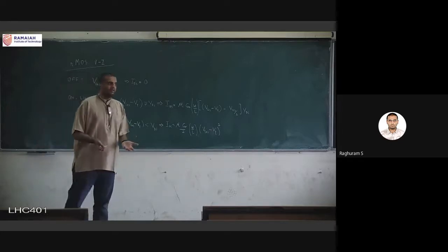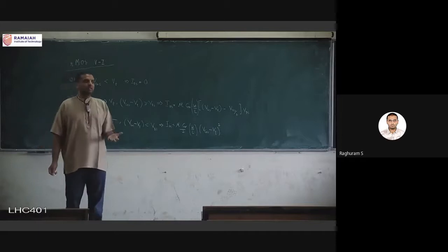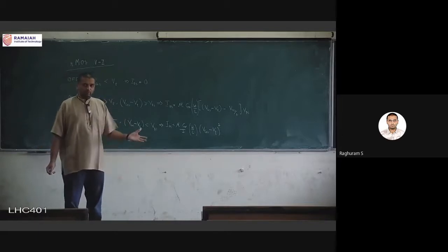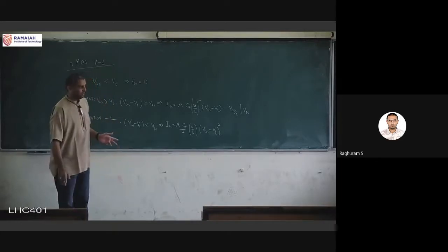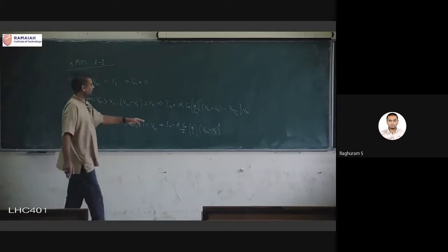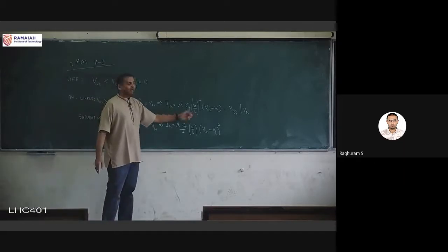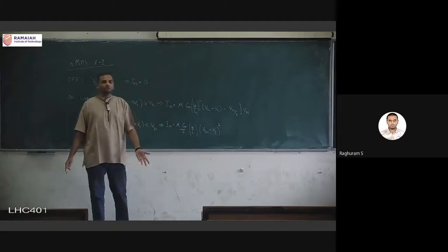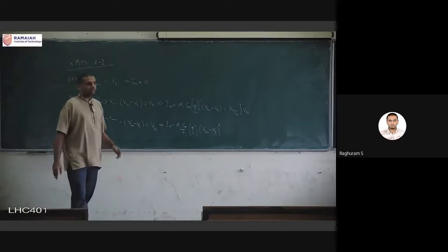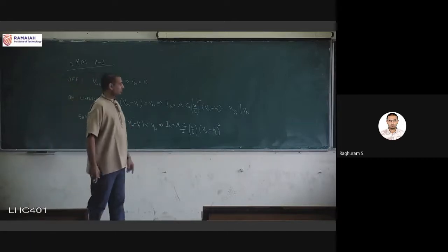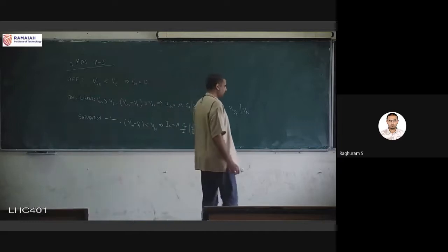Whatever value, for example, if some circuit is made with some default value of W, L, I said before also, we don't have to fix anything. Always the L will be fixed based on the technology. We don't have to vary it at all. And we don't want to increase the L, because if I increase the length, the current decreases, and we never want to see that. So the W, which effectively is the W by L, is the one that we can change. So this is the current flowing through.